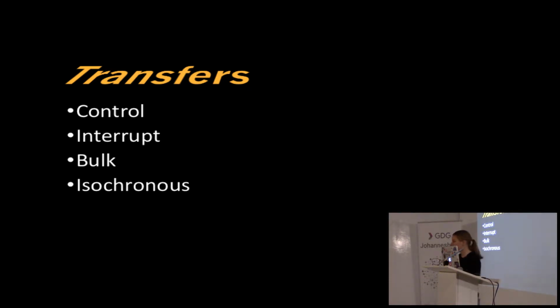And last, we have a very weird word, which I learned in the preparation for this talk, isochronous transfers. Isochronous transfers are for streaming audio and video. And they don't guarantee data delivery, but they do guarantee the amount of time that they're going to deliver the data in, because they reserve bandwidth on the USB bus.